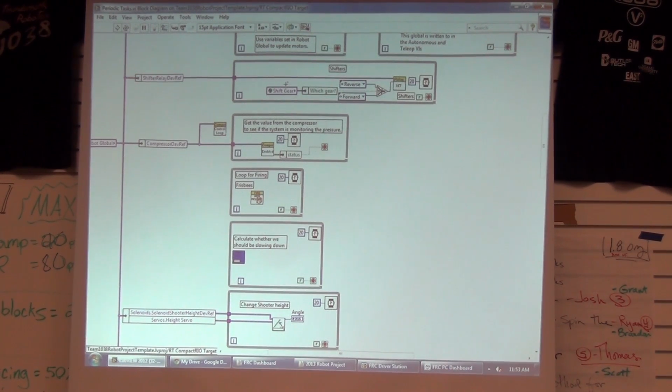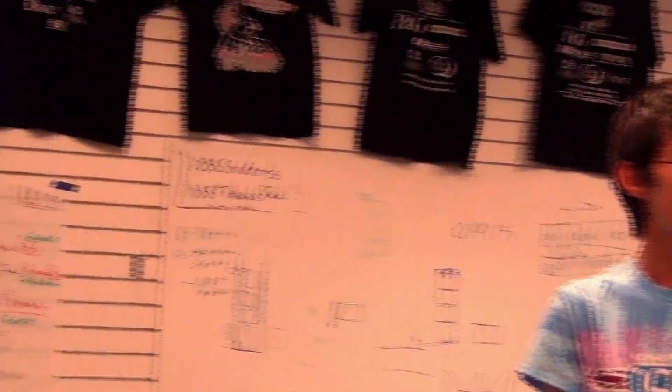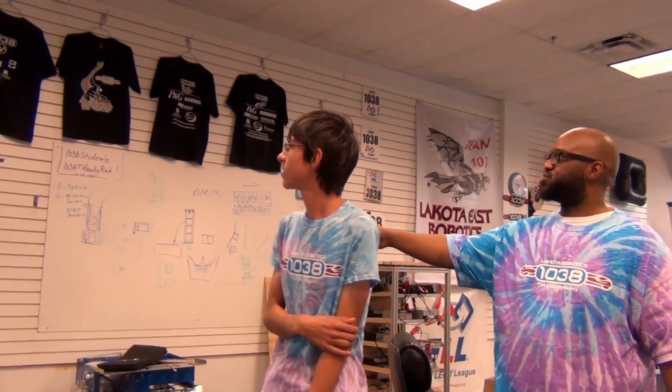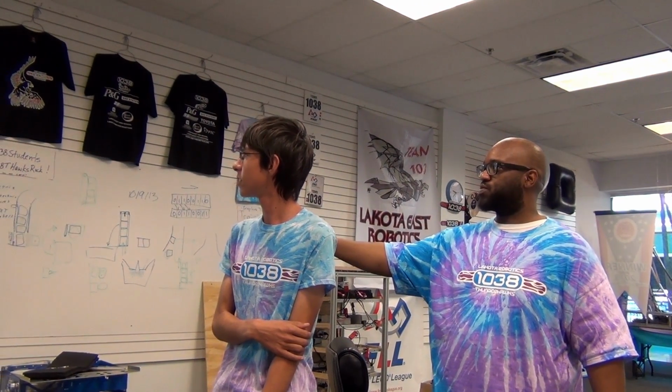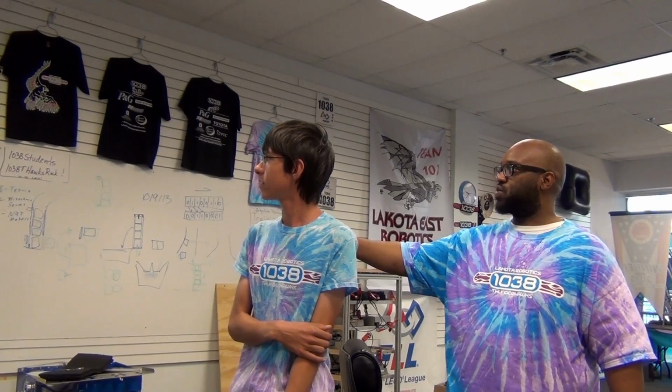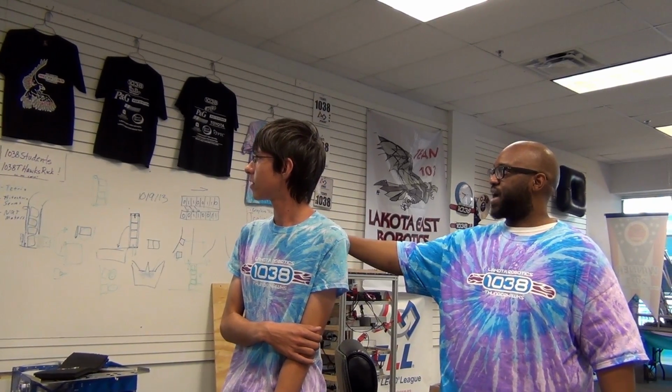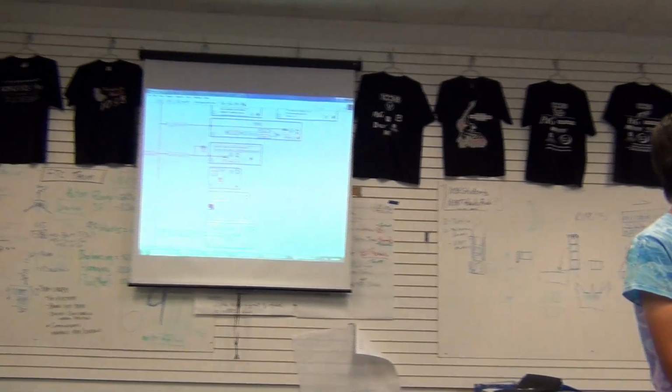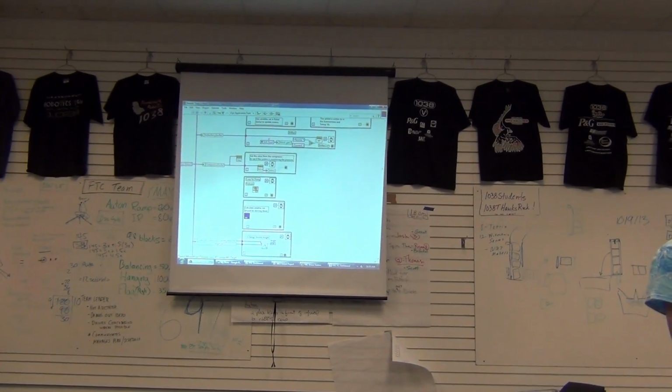Note, again, data flow. Each one of these loops is running at the same time because we're getting our references and passing them to each loop, and that happens pretty much simultaneously at this point. So we got our global data, we unbundle what we want, and then we pass it to our loop, at which point the loop is going to execute parallel to all the other loops.